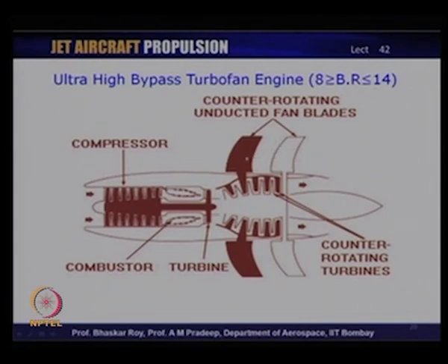As you can see here, one fan is mounted on one set of turbines, and the counter rotating fan is mounted on another set of turbines, and these turbine rotors are counter rotating, and the design actually excludes all usage of stators or stator nozzles. As we know, essentially these sets of turbines do not use any stator nozzles. They are counter rotating rotors enmeshed in each other, and hence they are statorless configurations.